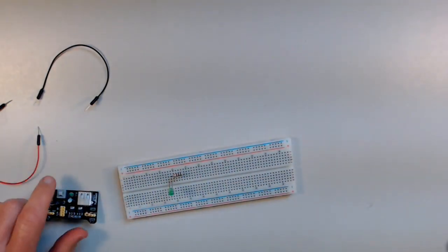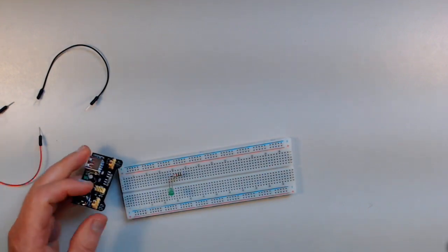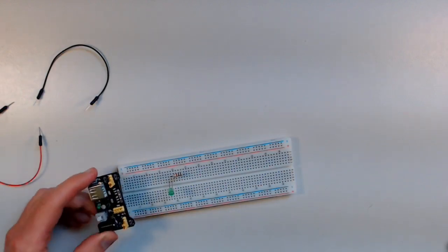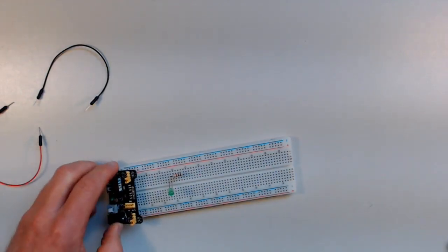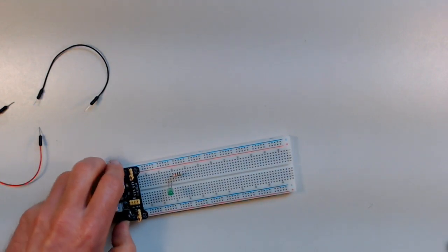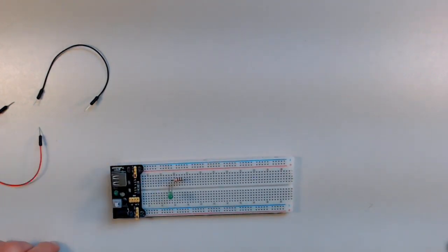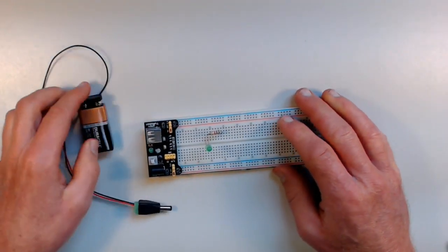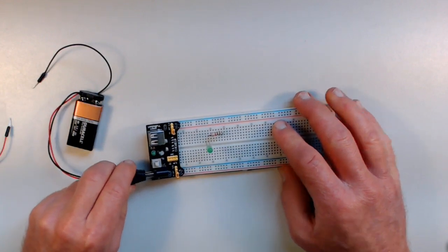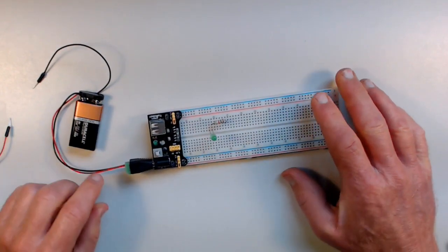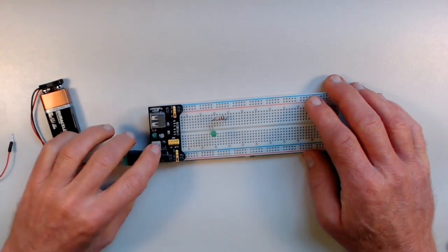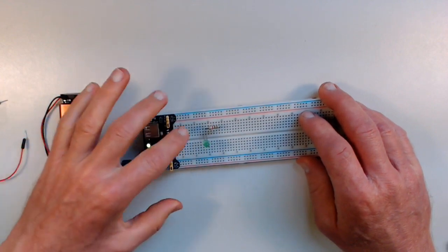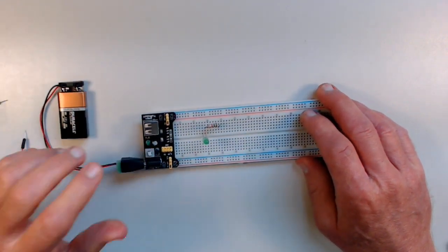And I need to connect up my power supply. Now, this little power supply is pretty nice because it provides the voltages for your breadboard, and it just plugs into the breadboard like this so that you can have power. And then you can run it off of a 9-volt battery. There's a 9-volt battery that comes in your kit, and you can connect that up to the breadboard like this, and that'll power it, and you can turn it on and it will power, and the little light comes on the power supply. But of course I haven't hooked up my circuit, so it doesn't do anything on the circuit yet.